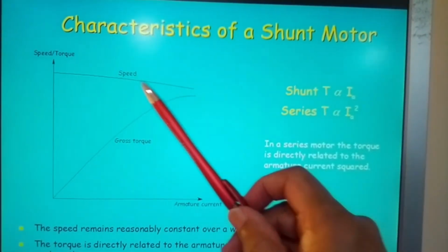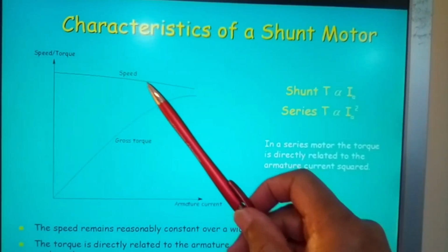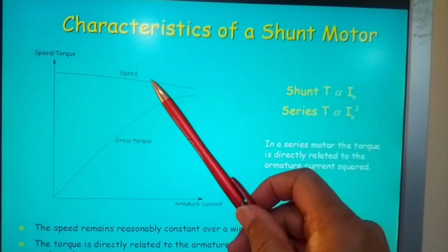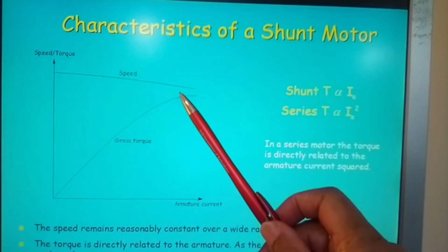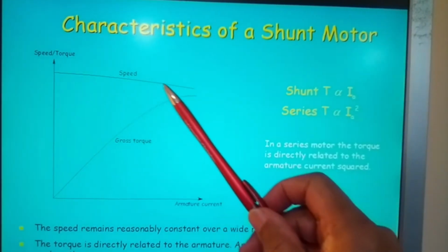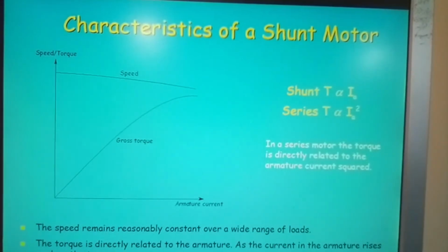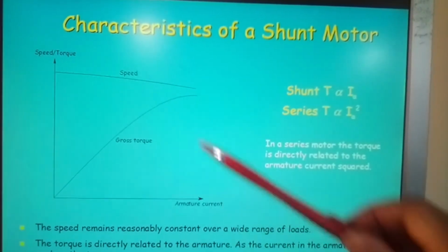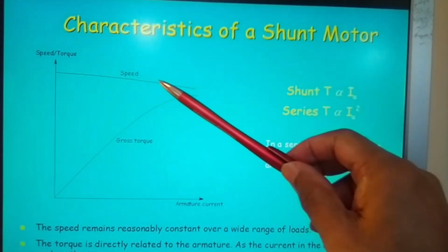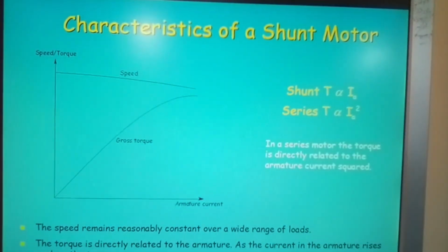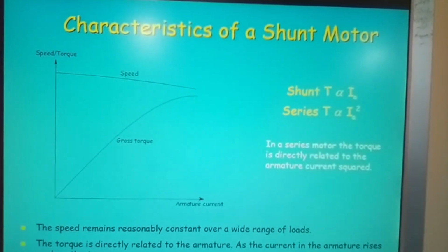Okay, in regards to the speed, at a certain point, in respect of torque and speed, one or the other will begin to drop. If the torque isn't sufficient, it will lose speed. Basically, okay. And you need to maintain the torque, and you can do that by increasing the current in the field at a point in time.